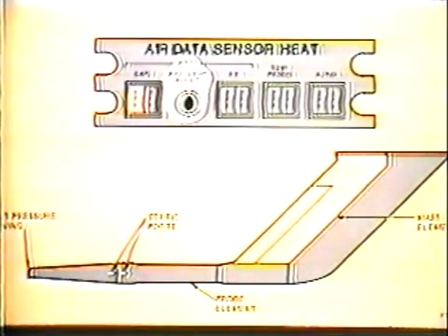When the mast light inhibit button is pressed, it inhibits the mast element signal. Therefore, if the mast element has failed, the off legend will extinguish. If the off legend remains illuminated, the probe element has failed. In the example shown here, the probe element has failed, so the off light would remain illuminated with the inhibit button pressed.